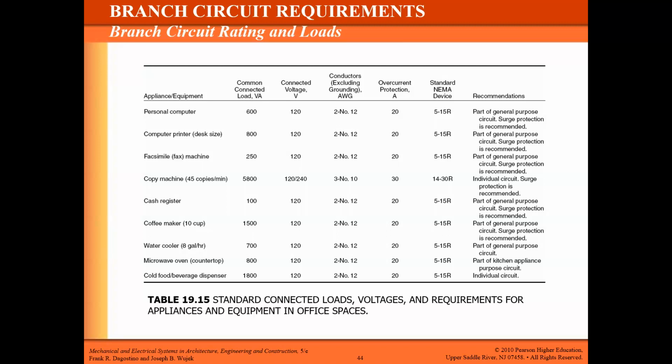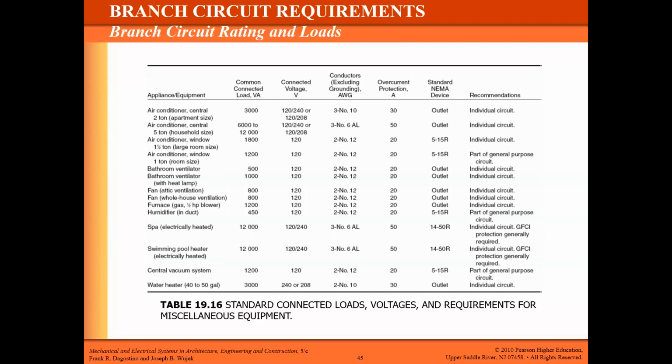So just be aware that if you are looking at a table for guidance, you may end up oversizing a circuit unnecessarily and just sort of leaving a little bit of money on the table that way. In other words, just make sure the tables you're looking at are current and sort of well aligned with modern appliances. And of course, there's one more table, 19-16 here, that shows some additional equipment. Now I'm going to go back a few slides because I jumped over a couple just to kind of answer that question I posed.